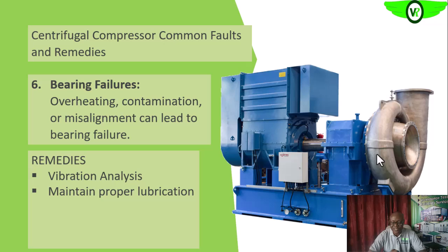If this rotating component, the bearing, is starved of lubrication, which is meant to reduce the friction at this component, of course that will increase the wear and tear, and that will eventually cause its failure. So we want to maintain a proper lubrication routine on these components, the bearings,